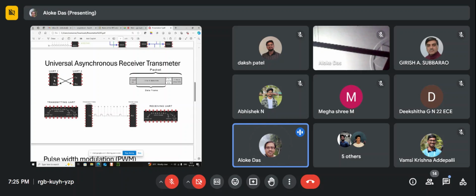Then only the communication, the handshaking, will be proper. Otherwise, whatever data is received by the modem will not be valid data. And we didn't get the right website, or the internet was not connected, there were a lot of problems. Sometimes on our own we used to change baud rates, like okay, it is not working, let's see whether 4,800 baud rate is working or not. Those kinds of things, some concept of a clock, that is baud rate.